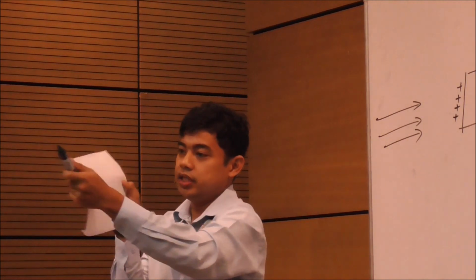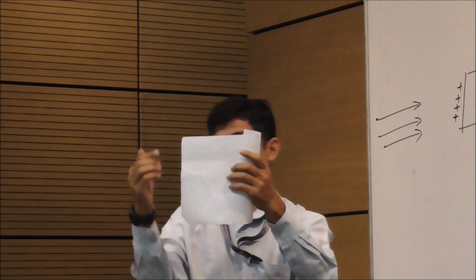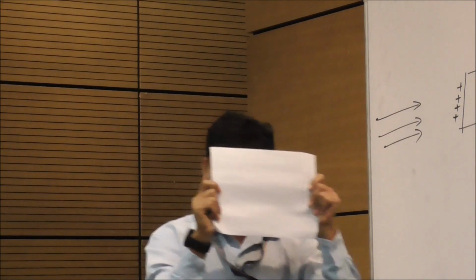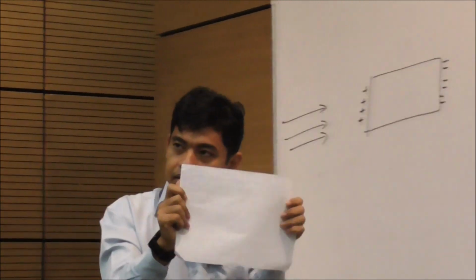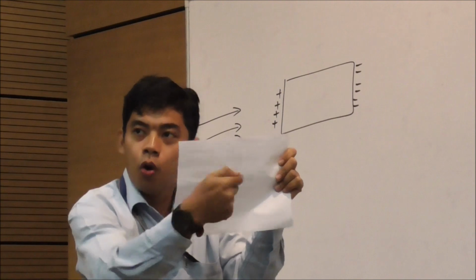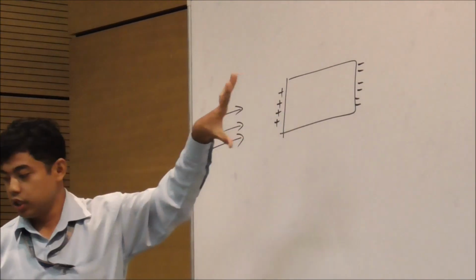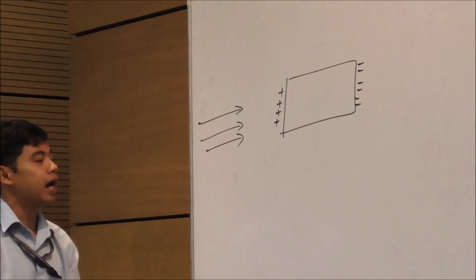But this deflection is, if it deflects, it means the pressure will be released. But if it's stiff like this, the stronger the wind, you will find the more forces is needed to hold it, right? The more forces is needed to hold it, which means the pressure difference will be higher, so the drag due to that pressure will be higher also.